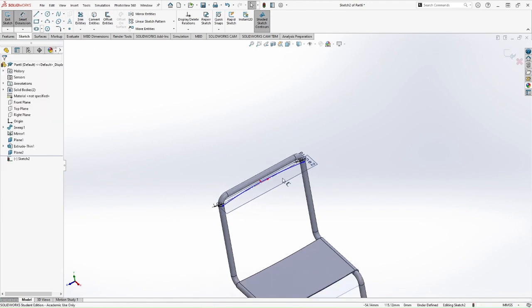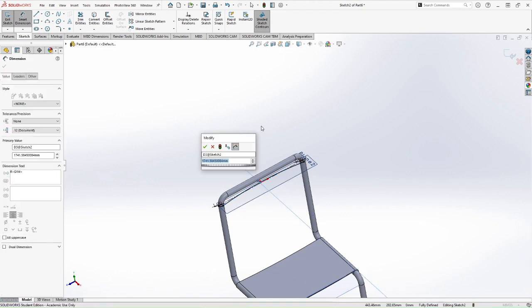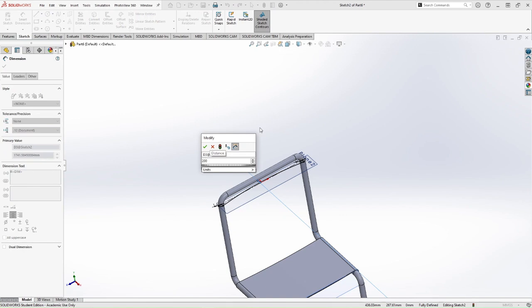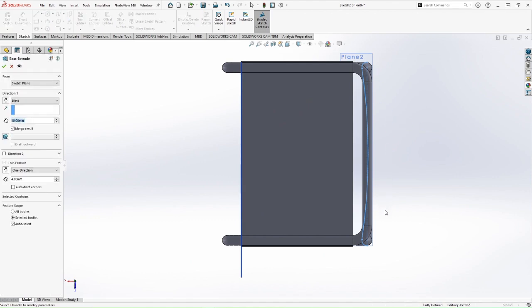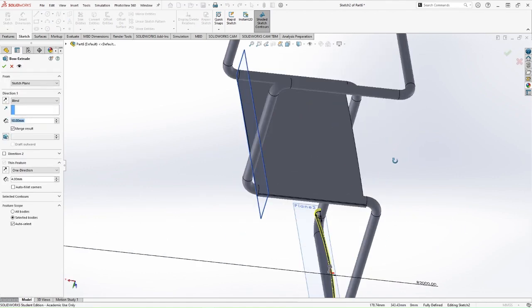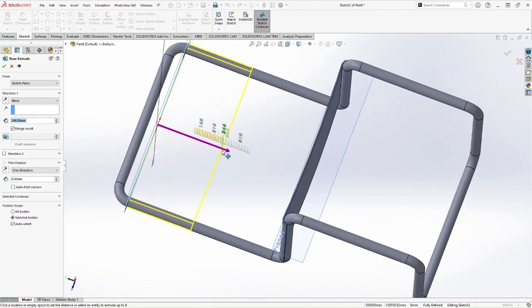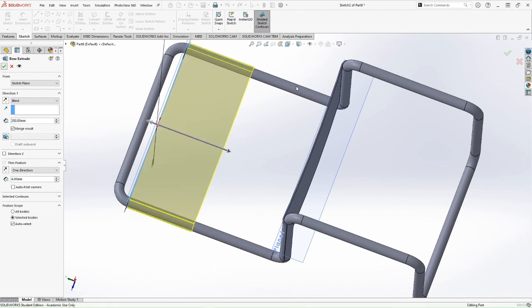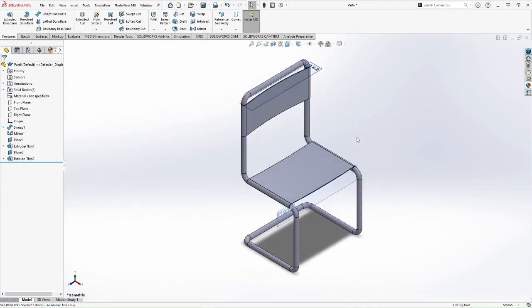Let's try adding the fillet. So first of all, let's do this basic design, and then we can identify if we want to improve the design. So that's 2000, and I'll simply exit the sketch, and that gives me the thickness. Okay, again I'm going to use the same thin feature, and I would extend it to, let's say, 300 or 250. 250, enter, enter. Okay, let's put isometric view, select isometric, and that's your chair ready.